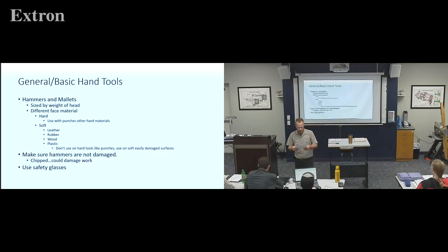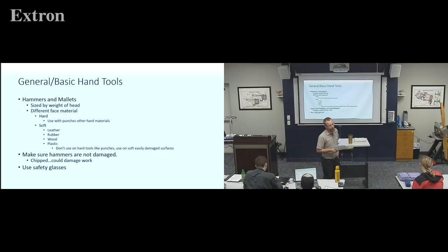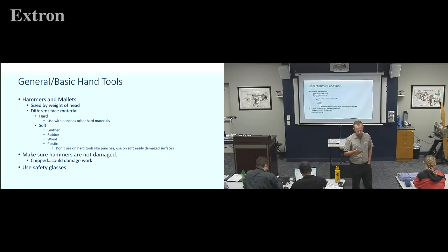Identification, installation of aircraft materials. So composites. We use 4130. Anybody know what 4130 is used for? Aviation 4130. Memorize that number, 4130. Maybe not for now, but for landing gear class. That is what your struts are made out of. 4130. Chromoly steel. Chromium molybdenum steel.